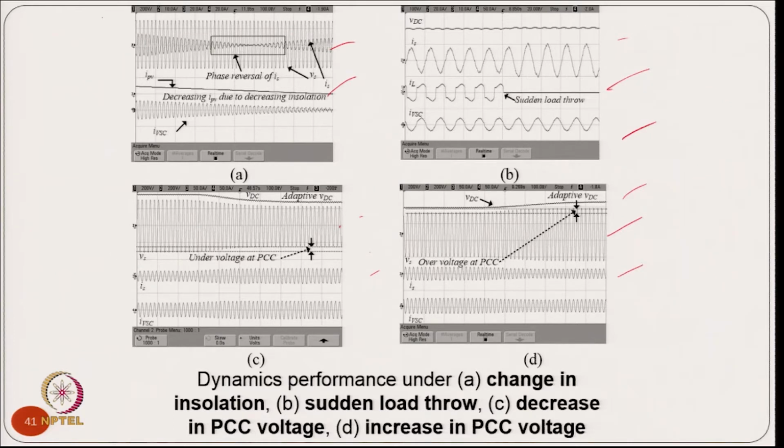So the control is made optimum in a way that the switching losses, or losses in the inverter, are reduced by taking adaptive DC link voltage, and we are able to compensate the local load also. We can do that 24 hours, utilizing the inverter for these other features to work as an active filter for harmonic elimination as well as reactive power compensation for the local load, from which the payback or the cost of the inverter can be recovered.